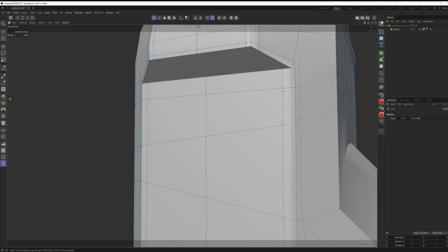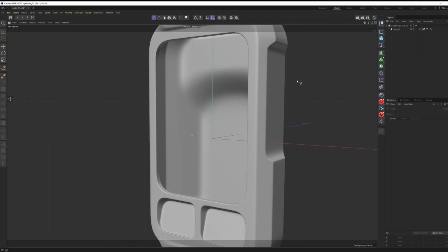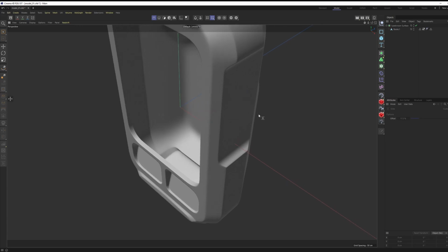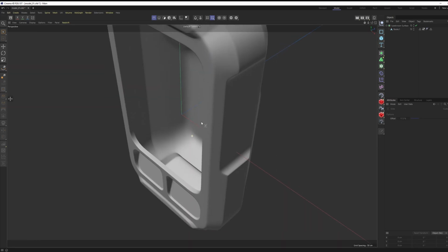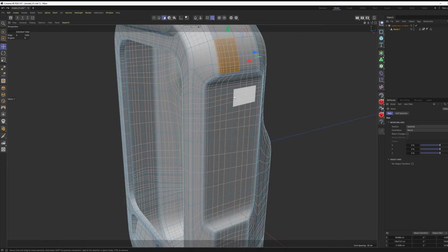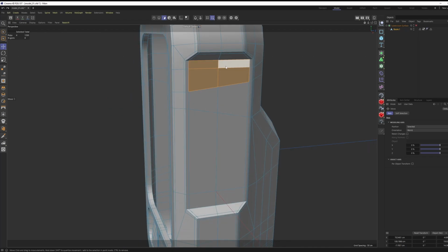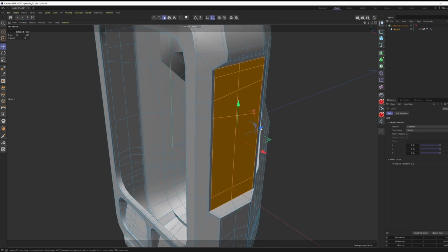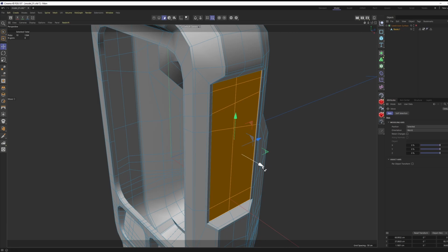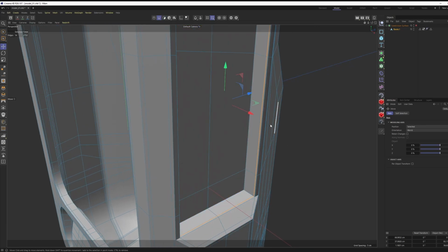You can lower this down, hit Q. Now this is looking perfect. Of course, this part should be empty inside of that. To do it, I'm just gonna select these polygons, hold down Control, and I'm gonna extrude them 2 times so that I can get this extra loop.